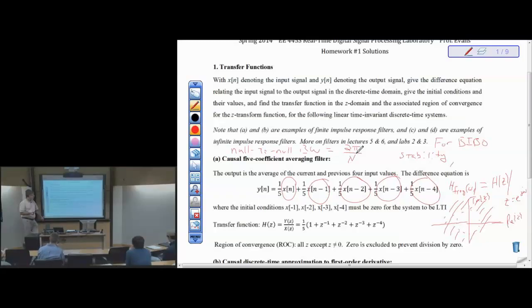And for 3-tap, it's 2/3 pi and so forth. So what does this mean? It means the more coefficients I have, the more narrow my passband is. The smaller the range of frequencies that go through the filter, and the greater the number of frequencies that are attenuated. There's a hand. Is this an ultimate what? Bandwidth.